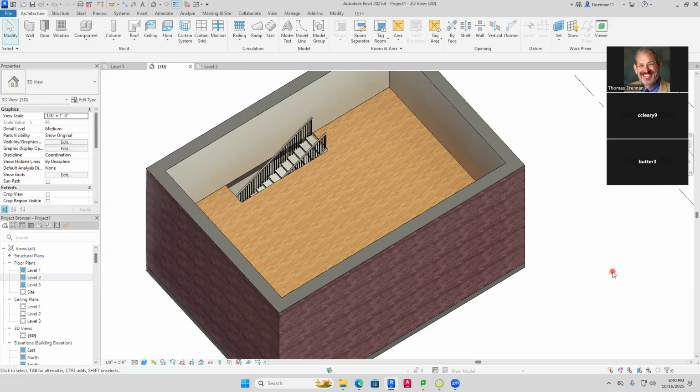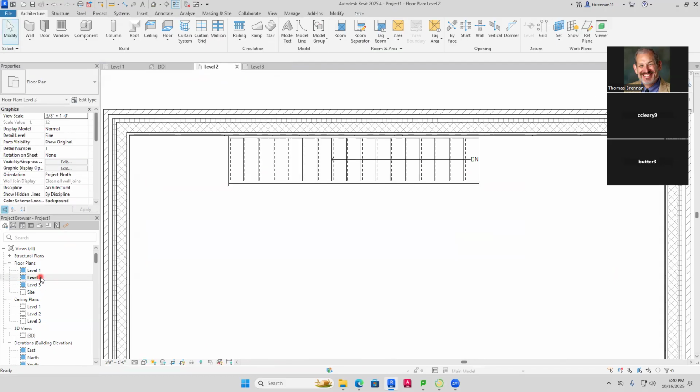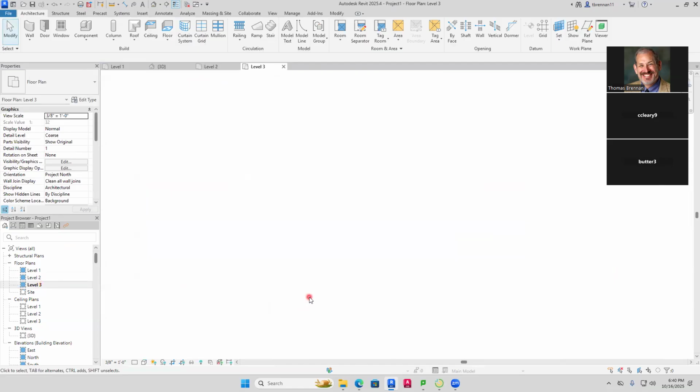If you want to, and you're going to do a third floor as well, you're going to run your stairs up to the third floor as well, up to level 3. So you got level 1 to level 2, so those are there. Okay, so that is where we have it. And if you can't see your work, you can go down here and just turn on your underlay. Underlay lets you see information that's underneath. So there's the underlay. Now, just to show you what I'm doing here, I went down here and I'm on the third floor right now. If I wanted the stairs to go up there, and I do, I'm here right now. And what I've got going on is I'm changing the ability to see it.